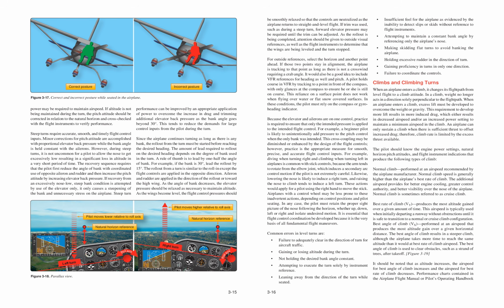Best angle of climb, VX, performed at an airspeed that produces the most altitude gain over a given horizontal distance. The best angle of climb results in a steeper climb, although the airplane takes more time to reach the same altitude than it would at best rate of climb airspeed. The best angle of climb is used to clear obstacles, such as a stand of trees, after takeoff. Figure 319. It should be noted that as altitude increases, the airspeed for best angle of climb increases and the airspeed for best rate of climb decreases.